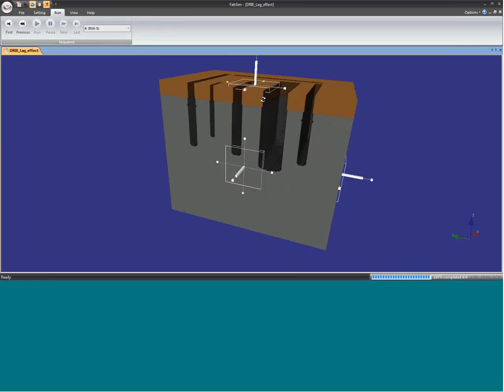You'll see that these larger holes are going to be etched more quickly than the smaller holes. And if we were to turn the resolution up, we could even look at some of the sidewall scalloping and some of the other phenomena that are present with a DRIE etch or with the Bosch process.